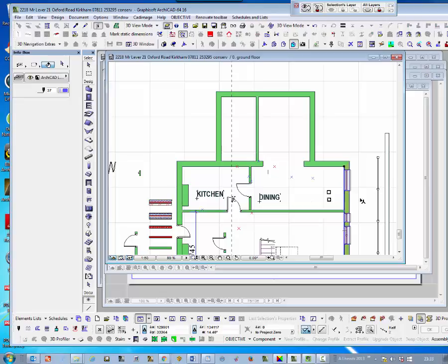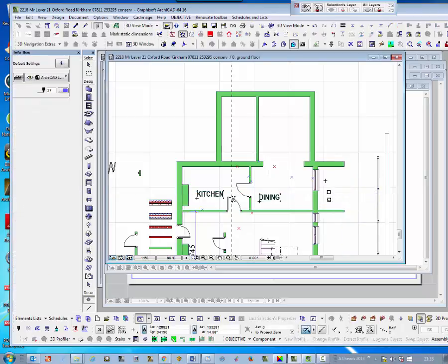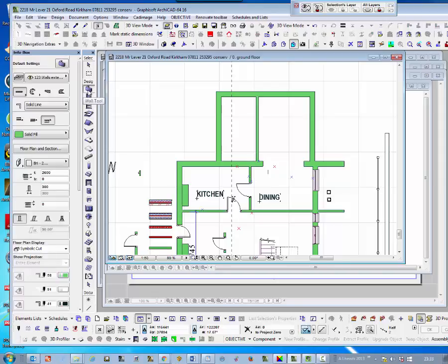So we can shift click on that, Control D, and move that edge. You keep your finger on the shift key, it will keep running parallel, but I want that edge to be on the hotspot there. Okay. I like before, using that icon, which is your wall tool. If we actually control click on a wall which is sticking out from somewhere, it will actually cut it back to that point. Control Z, right, that brings it back again.